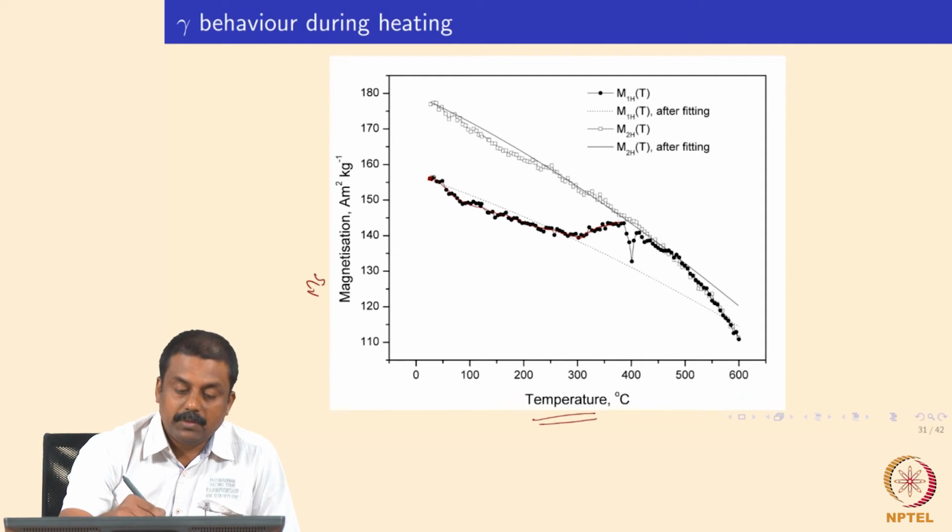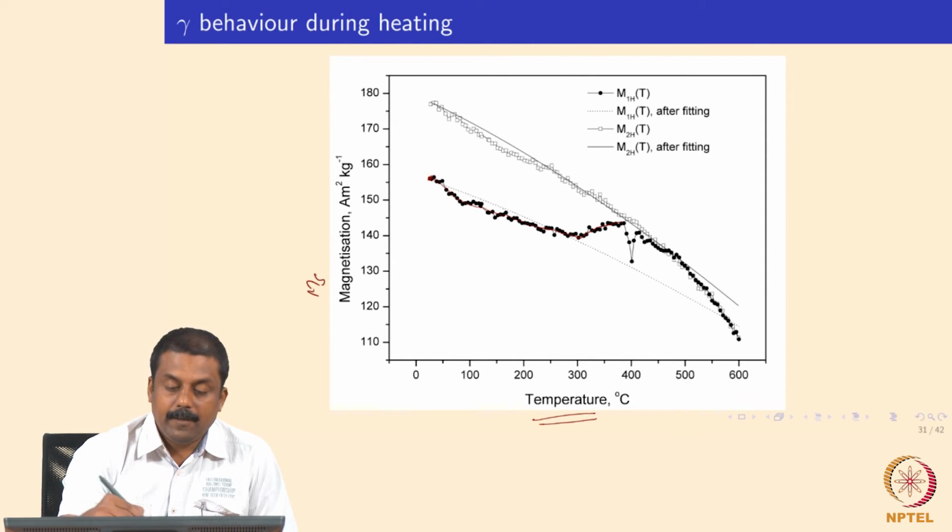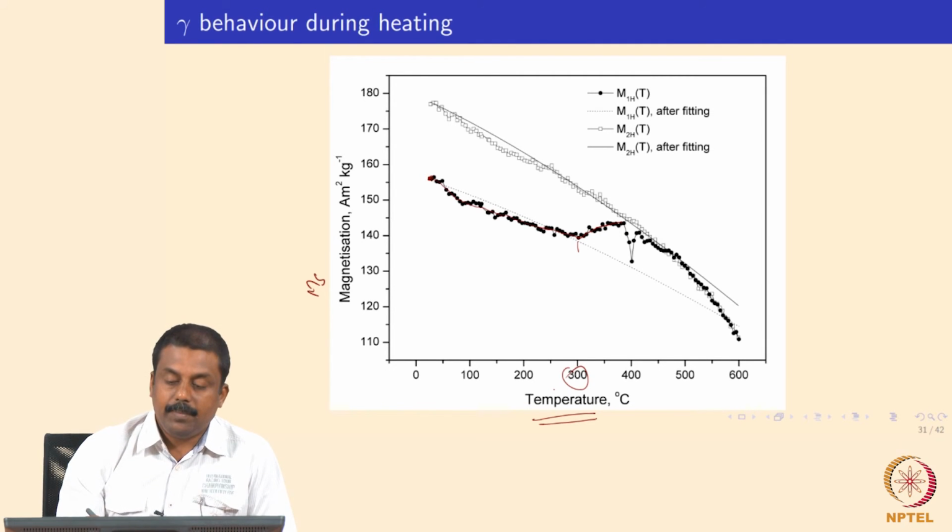So what this reaction implies is, you have a retained austenite containing TRIP steel, but when you heat it up, the mass magnetization saturation Ms suddenly increases upon reaching a critical temperature, for example in this case around 300 degrees centigrade. That means that the microstructure is becoming more ferromagnetic, right?